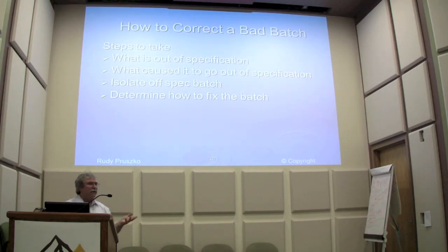And it turned out that he was actually bringing so much water in with his feedstock, and he wasn't distilling his methanol as good as he should have been. So he had a problem. He was bringing too much water in. That's where all the soap was. So I gave him do this, this, this, and this, and you'll be okay. He did them. He was okay then. So looking at FFA going in might not be actually the FFA that's in the reactor, because you're creating FFA.